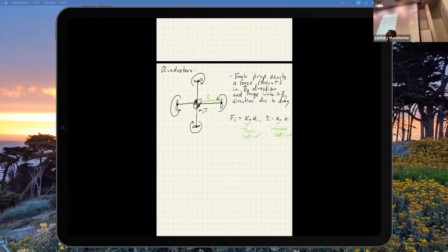So this is where it gets more complicated. This is assuming essentially zero inertia, that it spins up instantly when you apply torque like this. A more complicated model would account for motor effects and prop inertia effects, and what that ends up doing is you basically add states for these things, right?